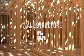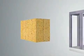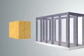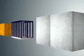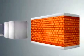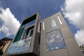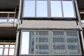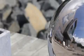Wall structure. The main structural wall can be a timber or metal lightweight frame or a massive masonry construction such as concrete or brick. This structural wall needs to carry the weight of the facade and resist the power of the wind. It should also be airtight, especially around openings such as windows. Airtightness prevents moisture ingress and ensures that the building remains thermally efficient.